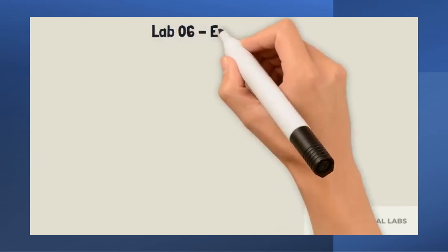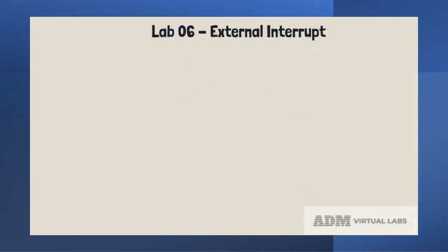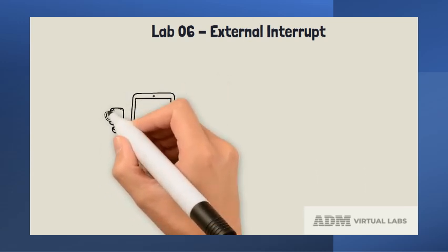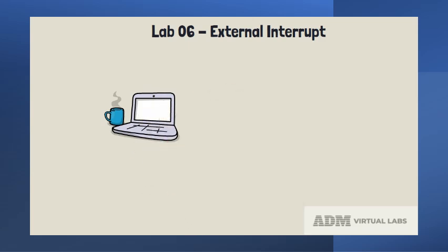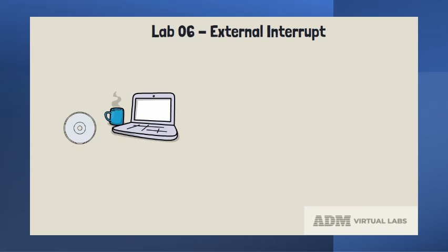Welcome to our 6th training session, where we will demonstrate how to configure a general purpose I/O pin as an interrupt input. We will then write an ISR handler for this interrupt, implement software debouncing, increment a software counter, and display the count value on LCD.